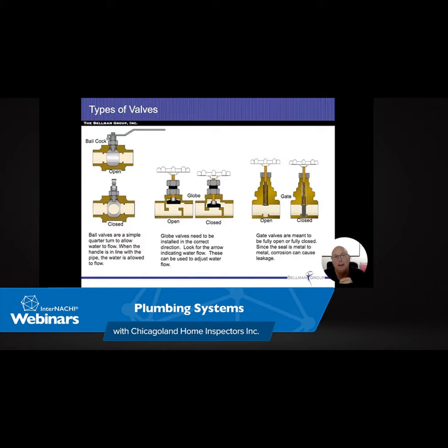All right. So it's not something that we want to put our hands on and start rubbing to see if we can clear it away to see the condition of the pipe. Once we clear it away, it's going to probably be leaking. So I would avoid it. What I want you to get out of this slide: galvanized pipe and black iron pipe corrode from the inside out, and this is what it looks like.